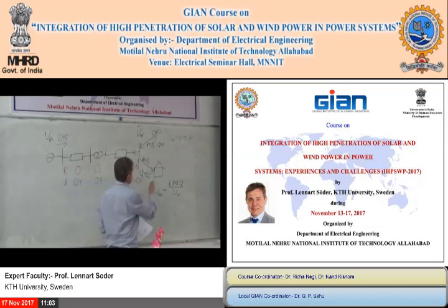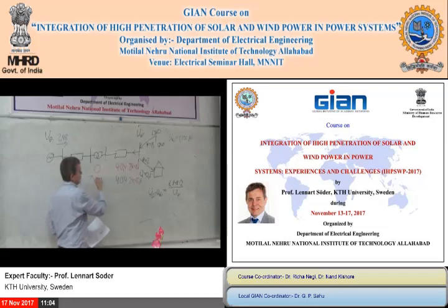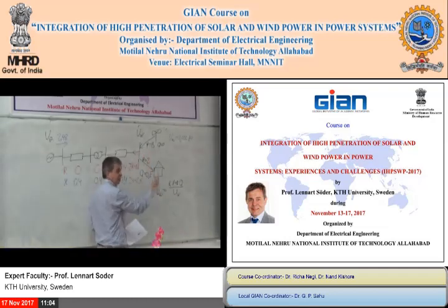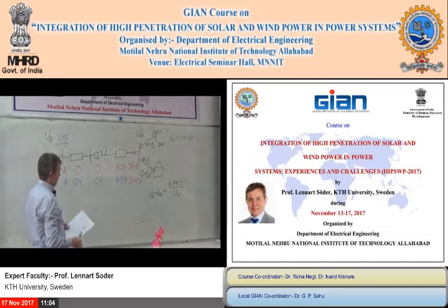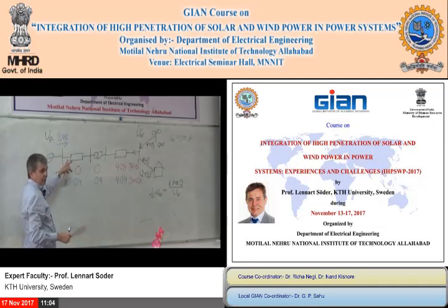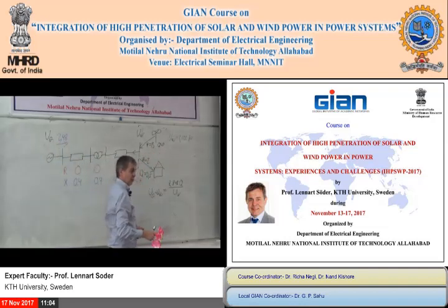If you want to decrease the voltage here, you should consume reactive power. If you consume reactive power there, then of course you will send in more reactive power here. So it's not possible to take that one down to 0, because then you would have to produce reactive power. And if you produce reactive power here, you will get even higher voltages, which is not possible. So in reality, if this is too high, you have to compensate it here with capacitors or something if you don't accept this one. It's not possible to compensate that out here since you already have too high voltages.